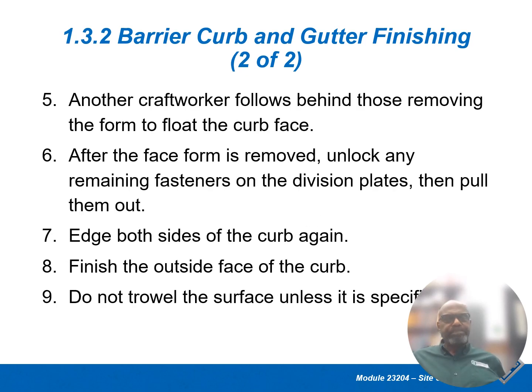Number 5, another craft worker falls behind those removing the forms to float the curved face. Remember, because of the stiffness of the concrete, you can take the form off, and now you can clean it up also and take care of any imperfections. Number 6, after the face form is removed, unlock any remaining fasteners on the division plates, then pull them out.